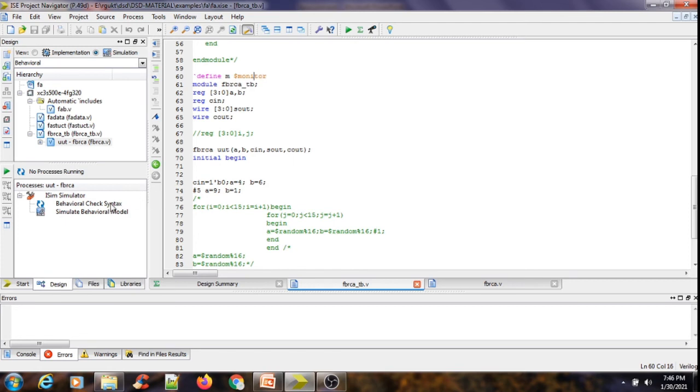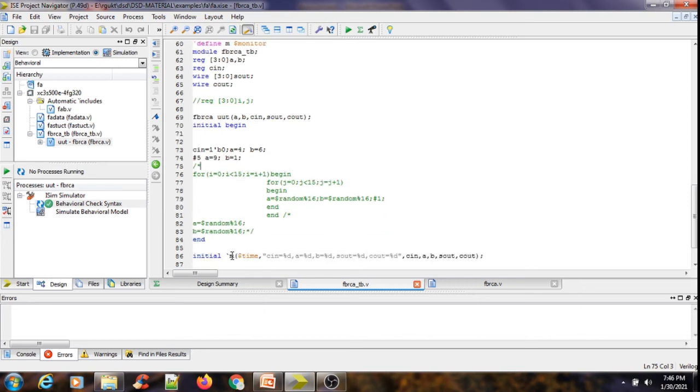So whenever I am compiling Verilog like this, okay, I have done compiling now, check syntax, it is correct. That means it is properly compiled. During compiling, the Verilog compiler substitutes the text of the macro as it is encountered here, tick M.